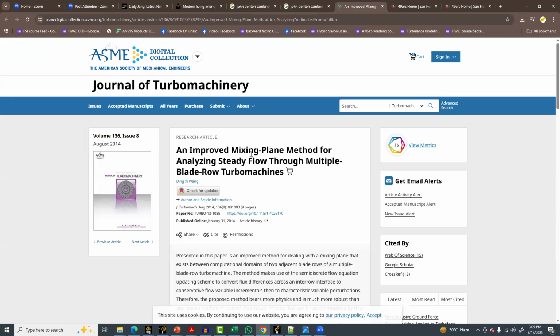The mixing plane is a method that does not require multiple blade passages. It mixes out the flow from the upstream component's outlet, for the downstream component's inlet. Mixing out means it will select different planes on your inlet. For the downstream component, at the different circumferential lines, it will apply the data on those lines as a single value for the single area location. Let me draw it.